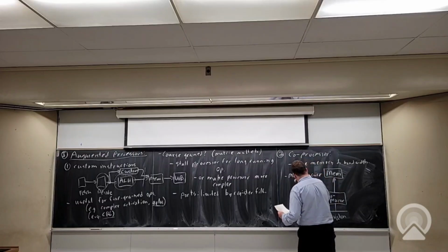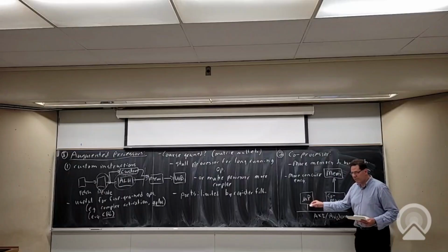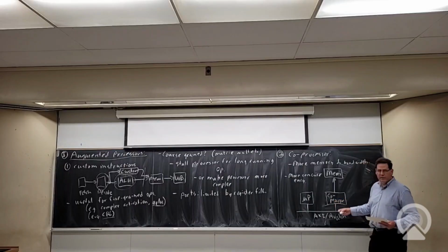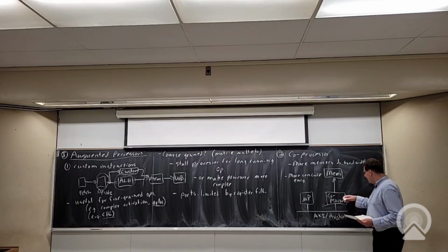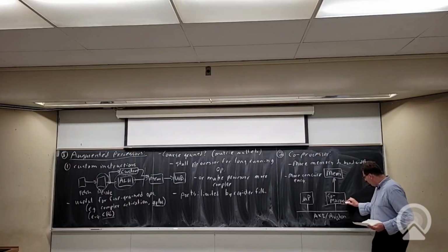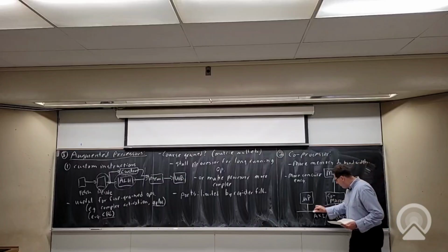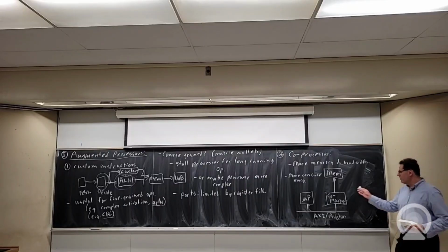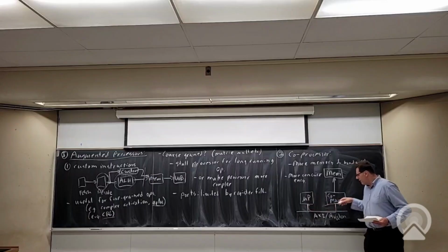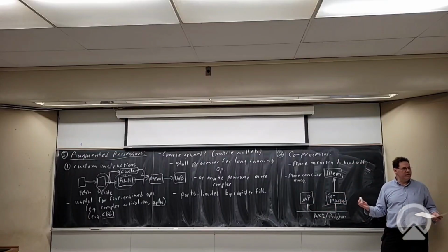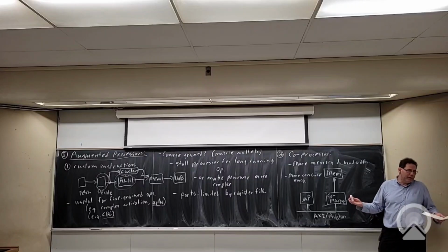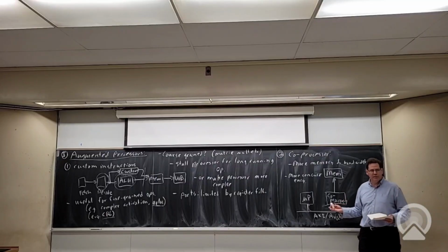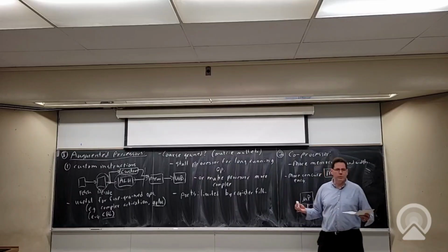Okay, so the way we can get more concurrency is normally the way these are hooked up is you write to a certain address, goes into this register here, and maybe that says go. And when it's done, it either just stores a done flag here, or maybe it writes back to some address and tells you, or interrupts you to say I'm done. But it's fundamentally, you send it commands and then you can keep going, right? There's no reason the processor has to stall. It could wait around and read some register over and over again for a done bit, but doesn't have to, right? It could just periodically check, could wait for an interrupt, could use all sorts of different techniques.